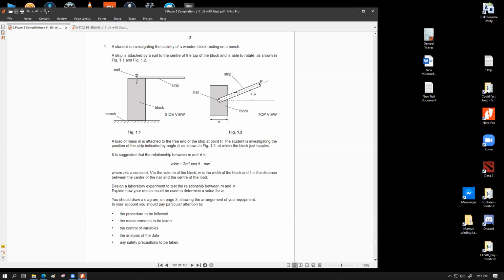That would be good. If you wonder why not 4 readings and measuring them from the center, that is exactly what we are trying to avoid. We are trying to have an average value that can give us an average of the maximum and the minimum reading. So if there is a possibility that this rectangular block is not made exactly rectangularly, so there is some manufacturing error and some parts are more polished than the other, measuring the dimensions on the side gives you a much more dependable averaging effect.